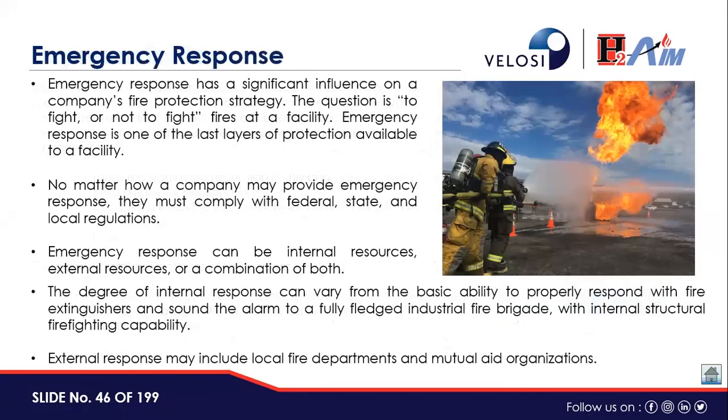Emergency response, as I said earlier, I explained a little bit. All major companies make a documented emergency response plan. They make various scenarios, for example, if there's a small fire, a big fire, a BLEVE, or a boil over of the tank. In those scenarios, in addition to the existing firefighting system, the industry or plant may call for the civil defense force or other security forces or other external help, and that would also be provided for.